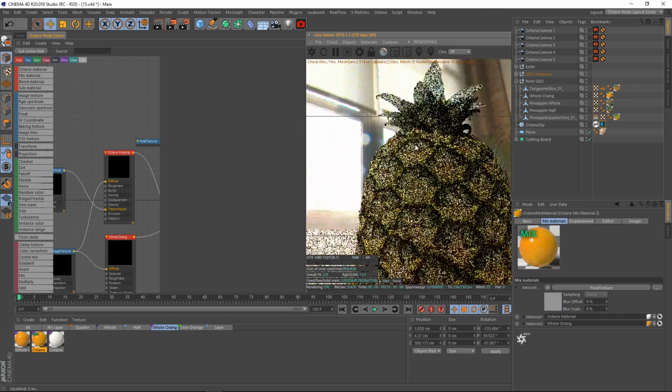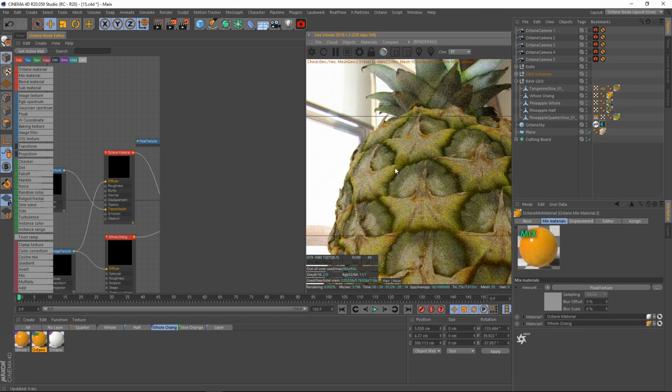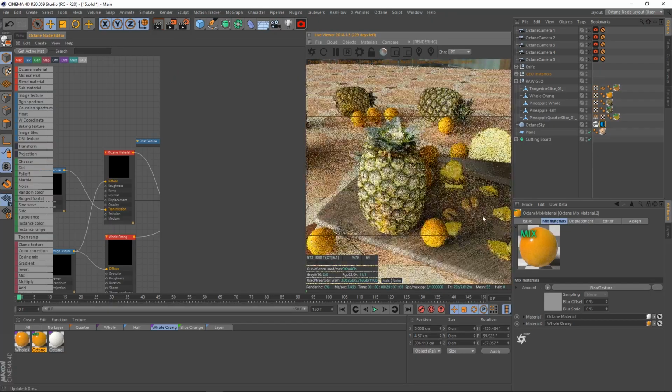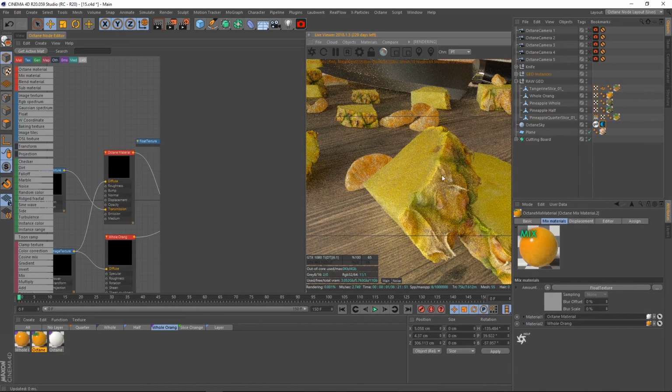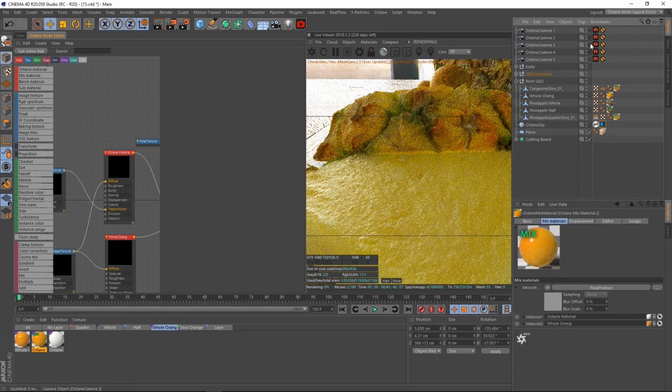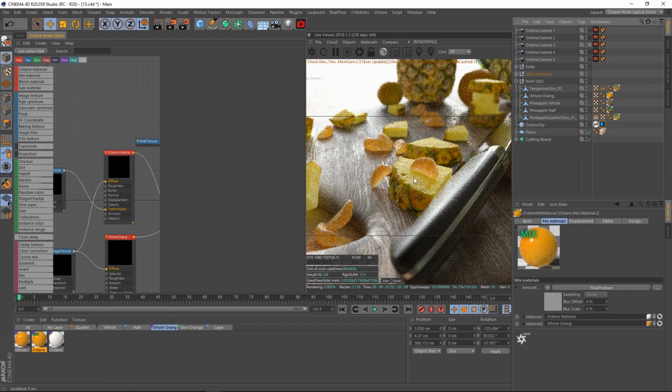A pineapple is pretty rough looking, right? A pineapple is not very reflective, so I definitely don't need any subsurface scattering, I don't need a specular material on it, right? Not like the slices. The slices had to have a specular material because they had liquid on them. So we needed that nice kind of liquidy look for the reflection and stuff of the pineapple. If I go over to shot 3, it'll show it off again. Again, this is very wet. There's liquid. We just cut this slice open. So that would show up there, and that gives that detail. We can see the bump map and the displacement showing up really good for this wood grain here. And you can see that really gives some life to our pineapple slice here.